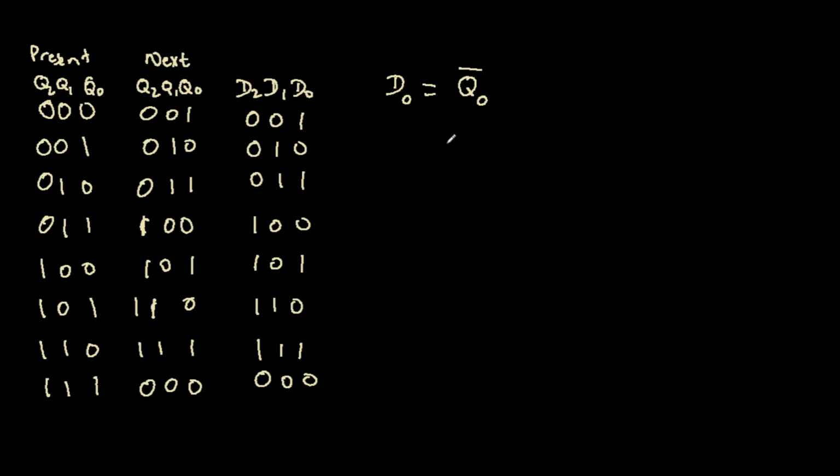And that makes perfect sense, because your first flip-flop, your LSB, is effectively just a T flip-flop. So the Q0 bar gets connected to the input of that flip-flop, and it will toggle at every point in time. Your LSB will always toggle whenever there's an active clock transition for this counter.